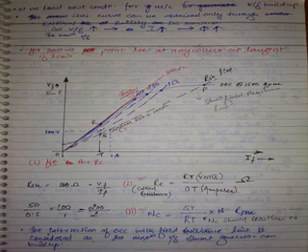Previously, there is a shunt field resistance line here. OCC at NC is making a tangent. Now, if you drop a perpendicular exactly, if this is R, let us say this is S, and let this be T. Length of RT represents 1500, the rated speed. Length of ST represents what? Critical speed.